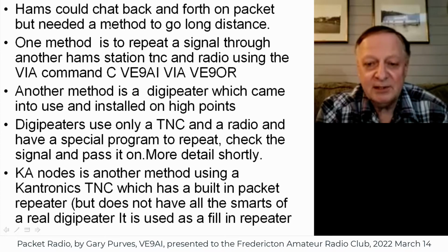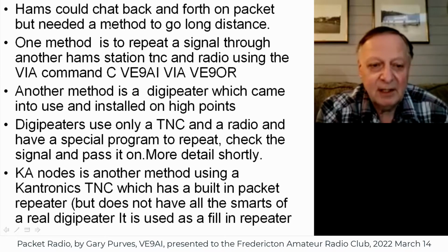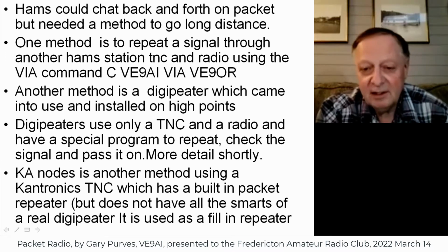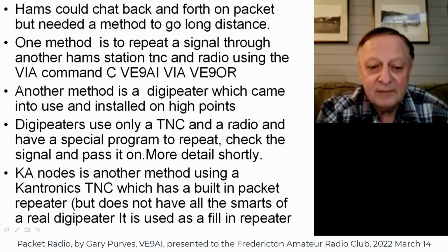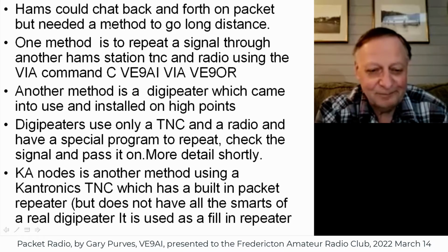Another method is the Digipeater, which came into use and was installed at high points. Digipeaters use only a TNC and a radio. They don't need a computer or a dumb terminal when being used that way, and it has a special program to repeat, check the signal, and pass it on. We'll have more on that in a bit.